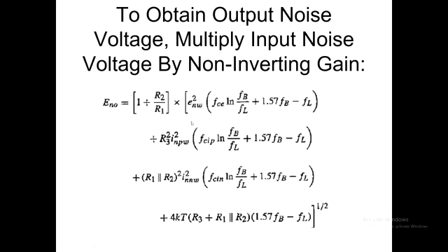So if you like, everything inside the square brackets here, which has got four entries in it, all that stuff is as if it's the spot noise at input multiplied by the bandwidth at input. We can call this capital E, subscript N, I for input. That's what we would see at the input.